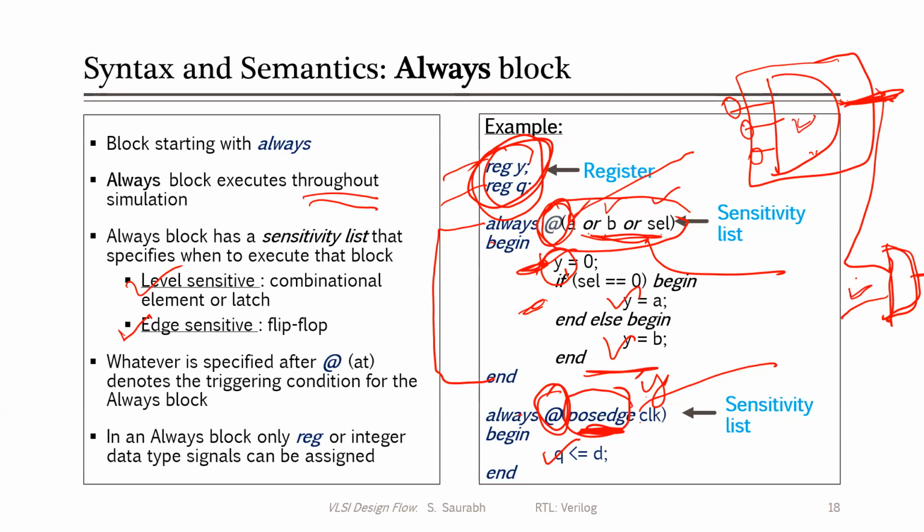I'm just giving you a description. It is not that this is directly used in modeling in Verilog, but I gave you an example where the written value of one always block can be reused, or rather, the change in the value of a signal in an always block will trigger another always block.